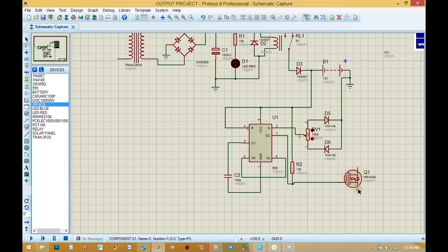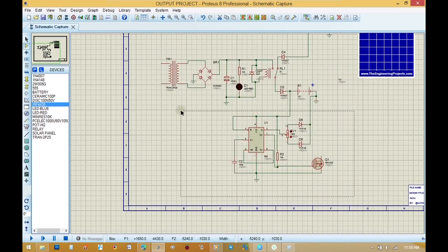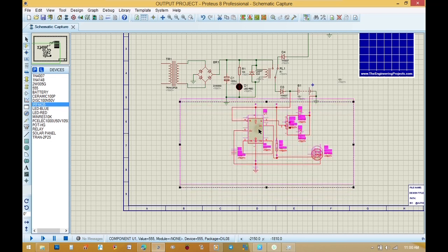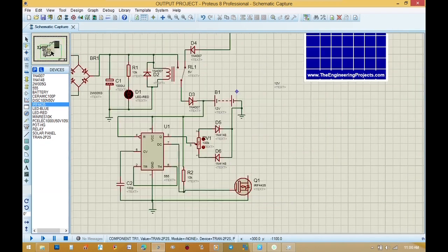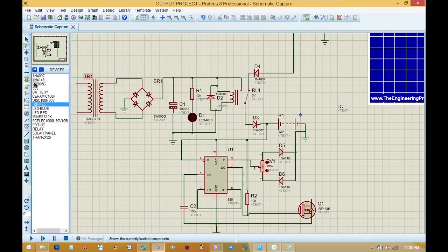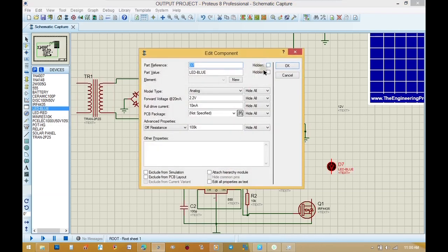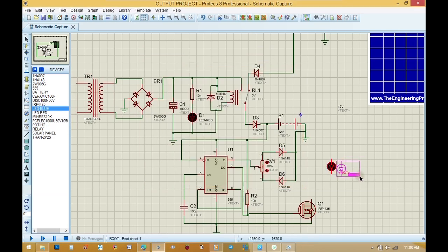If it is a normal standard astable multivibrator, we bias pin 6 and pin 7 with a voltage divider resistor and then pull it up to VCC, so that when it charges, because pin 7 is the discharge pin, it charges from R2, that is the resistor connected directly to pin 6, and it will be discharged.